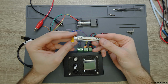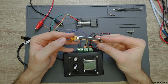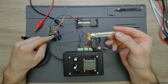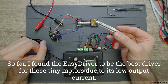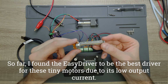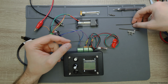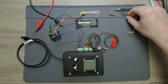The most important thing about these is that they are very weak, and by weak I mean that they need very tiny current to drive. So actually this DRV8825 is a bit of an overkill. I should have used the Easy Driver, which runs them perfectly, but I don't have a working piece now. So I will drive it with this driver, but for only a short amount of time.